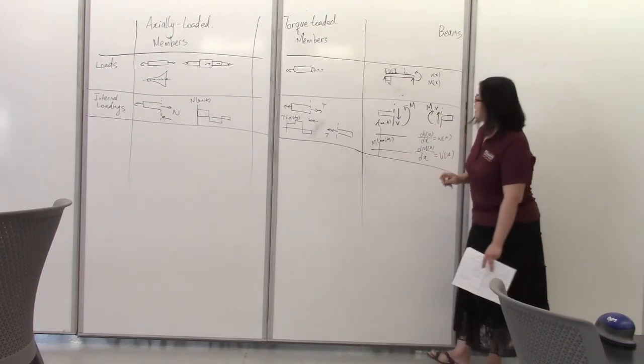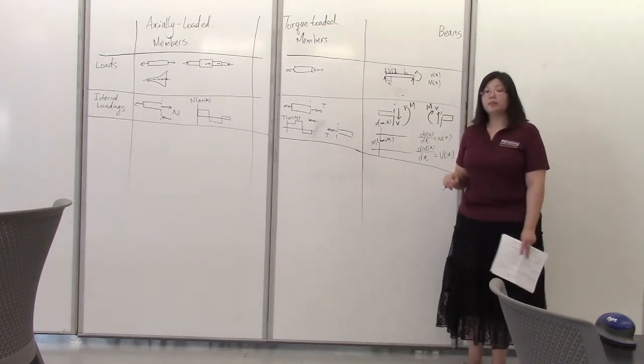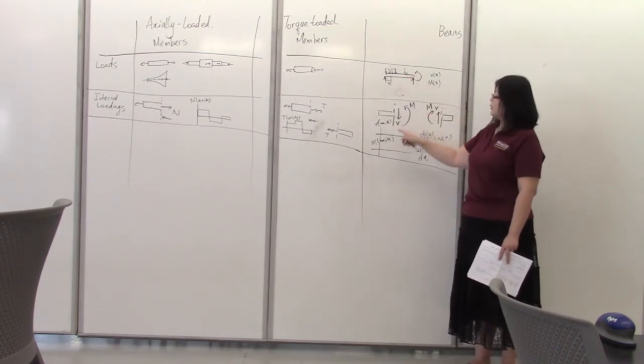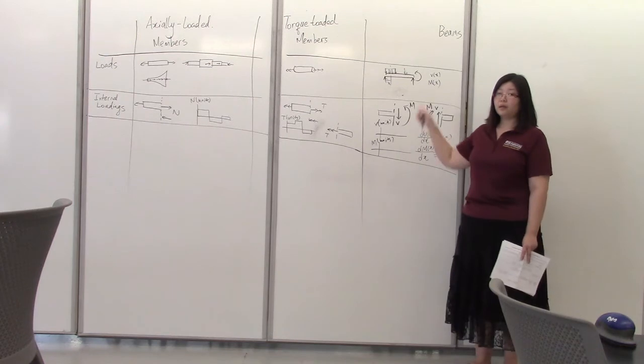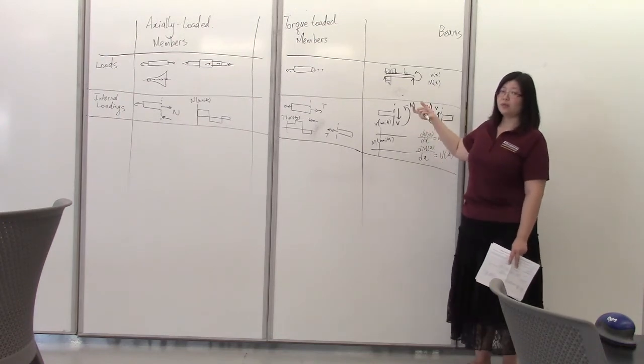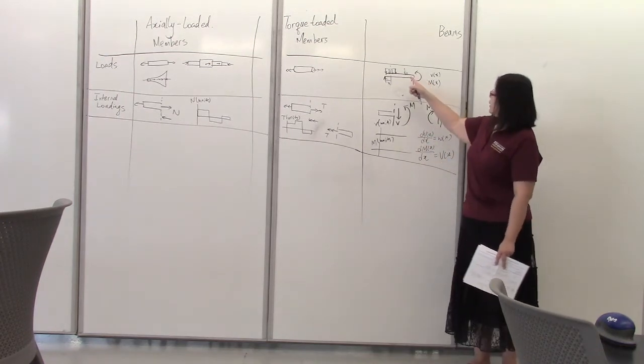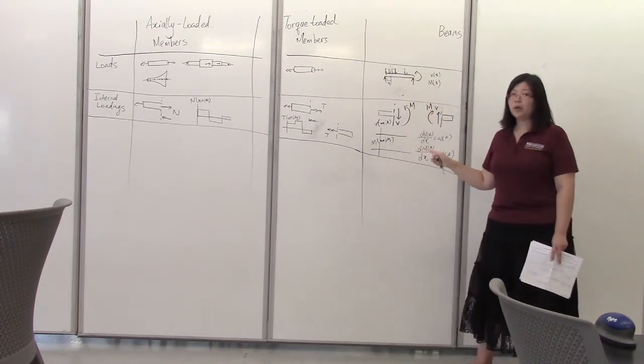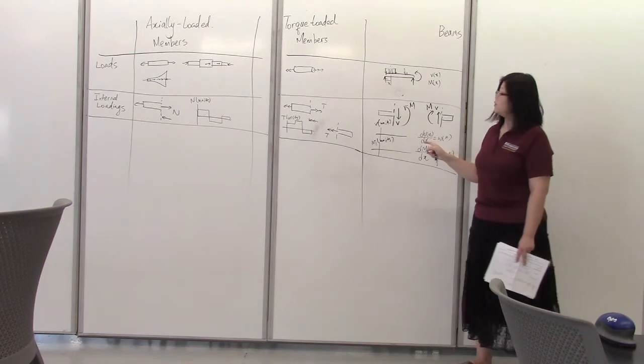Okay. Finally, there will be jumps when you apply a point load or a bending moment. Wherever there is a point load applied, V shows a jump in the direction of the point load. The amount of jump equals the magnitude of the load. But it doesn't create a jump on the M diagram. It would create a turning point, but not a discontinuity.